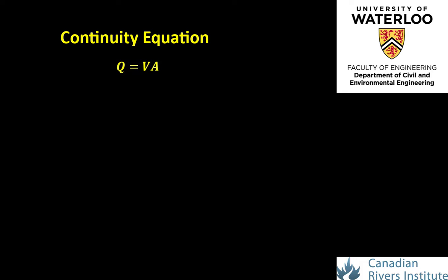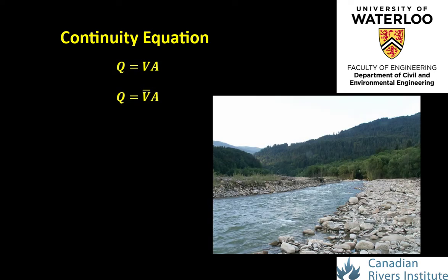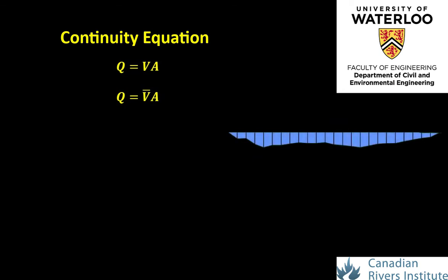The discharge equation can be represented as the product of the average velocity, here denoted as V bar, and the flowing cross-sectional area at the given instance in time, whereby V bar simplifies all the spatial variations in the velocity field into one single representative value. However, in determining discharge, rather than, for instance, estimating the parameter such as in a modeling or probabilistic application, its quantification must recognize the spatial variability of the channel's bathymetry, morphology, bed material, and submergent vegetation, which can generate spatial differences in the velocity field and cross-sectional attributes at any one given location.